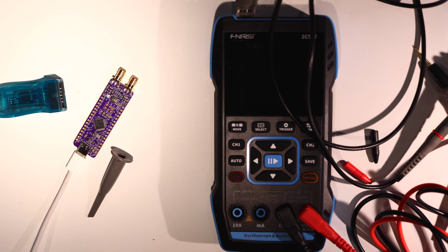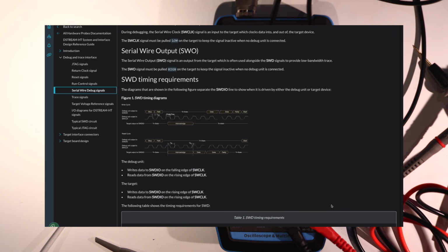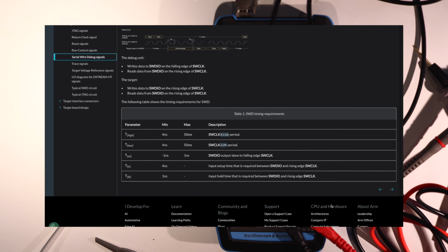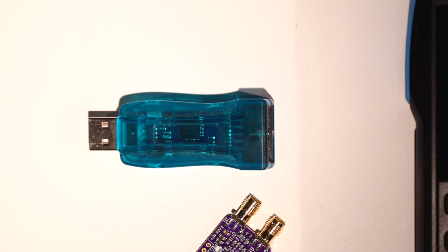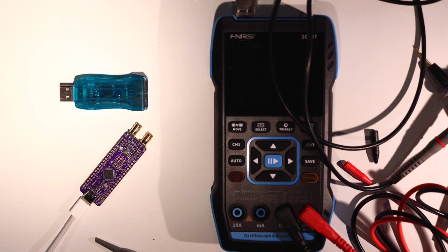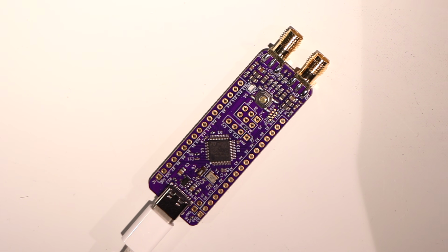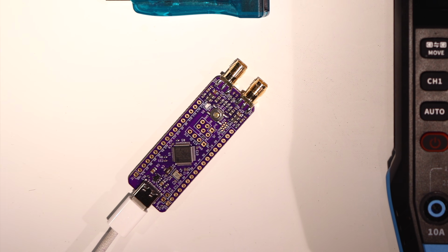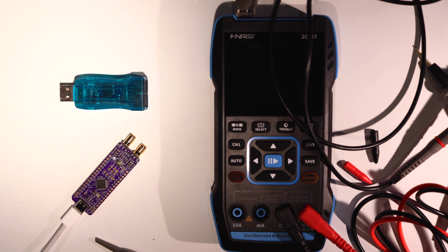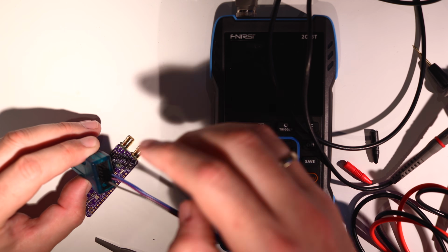Programming STM32s is either done through an on-chip serial bootloader or serial wire debug, which is a common standard for programming ARM core MCUs instead of JTAG. Luckily, these ST-Link V2 dongles are super cheap and also come built in with even the cheapest of ST's development boards. I've put optional jumper pins on the board that you can use to start the serial bootloader to just use a normal UART or debug code from SRAM, but the cool thing about using the ST-Link is it only requires ground, a clock, and an I/O pin to program the built-in flash.